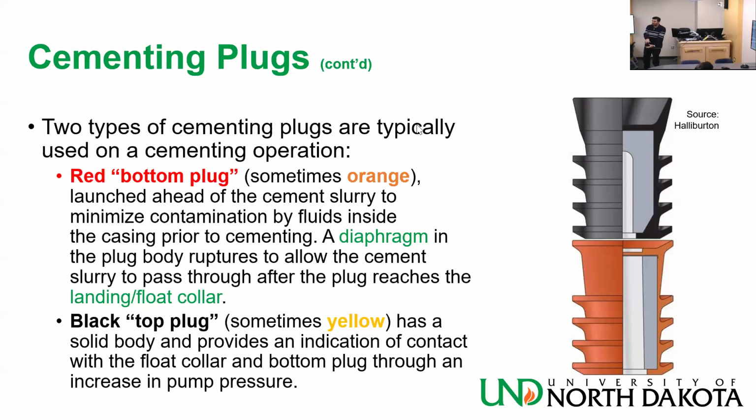the float collar, the bottom plug, and the top plug. You're going to have to drill through them, right? These ones, they are rubber. You can drill through them fast. You will drill through them fast. And then you're going to drill through the casing, the float collar, and the casing shoe. It's not going to be that easy, but it's going to take like 3 hours or something to drill through them, maybe more, maybe less. But this is when you did it right.